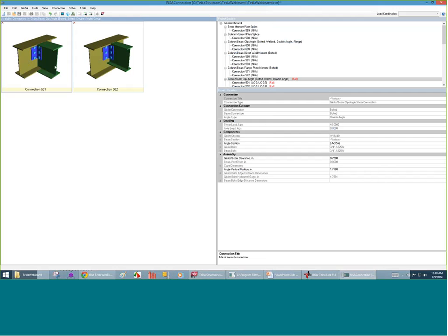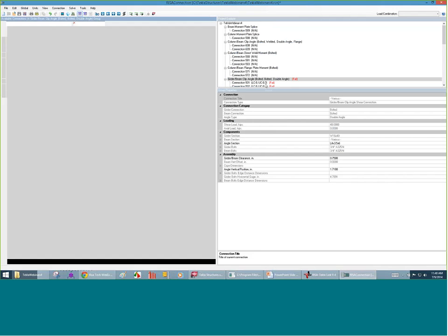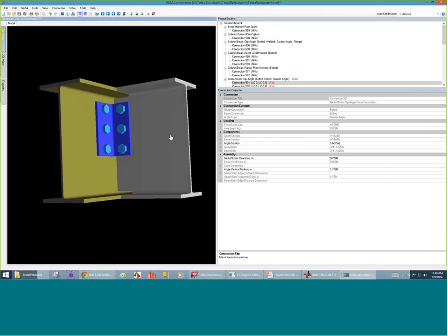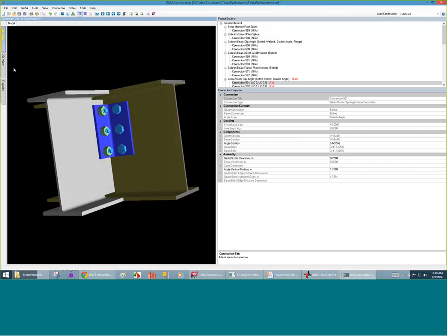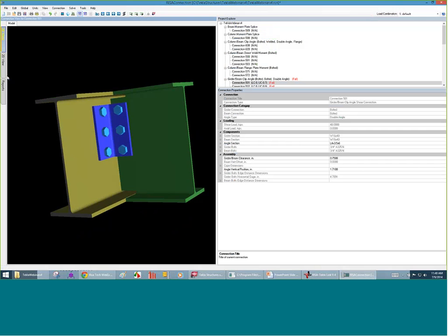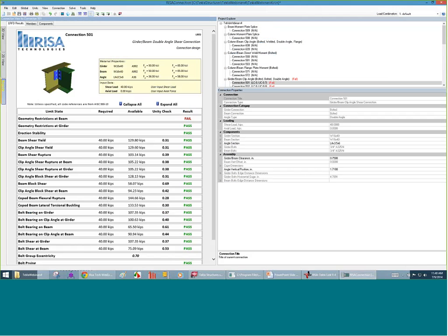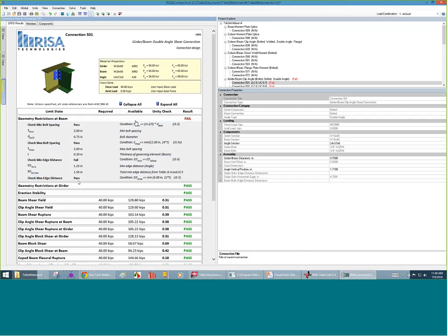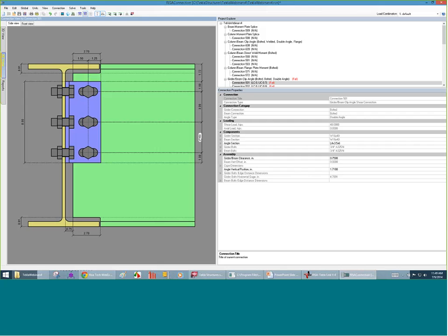So there are some failure problems in here, and we can see again those failures are going to be geometry failures. Looks like I have some problems. I'm just doing the same exact problem there. So probably what you do most likely is lay out some better rules over on your Tekla structures so you wouldn't have these failures in your edge distance. But again, so easy to make that quick change. Okay, so we know we need to hit the edge distance a little bit better.